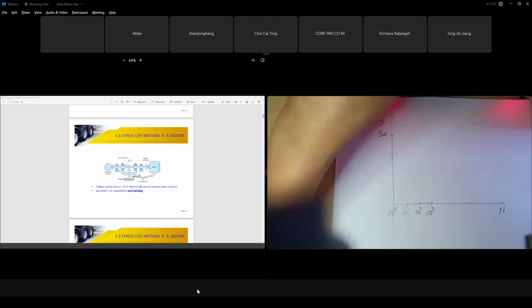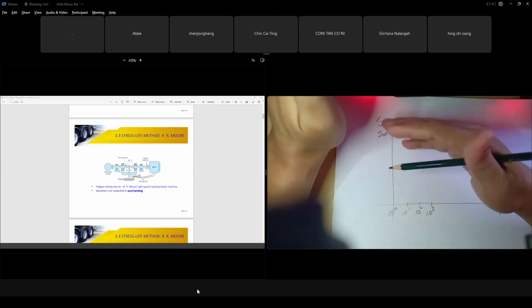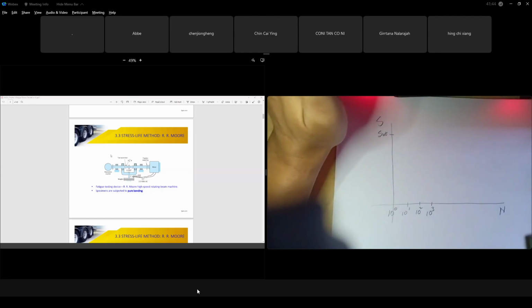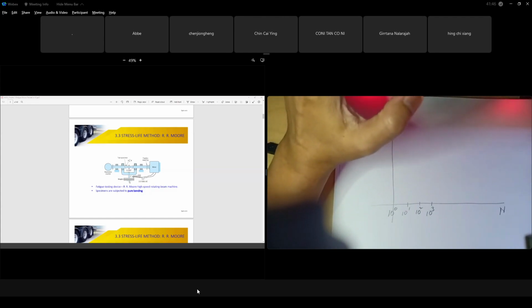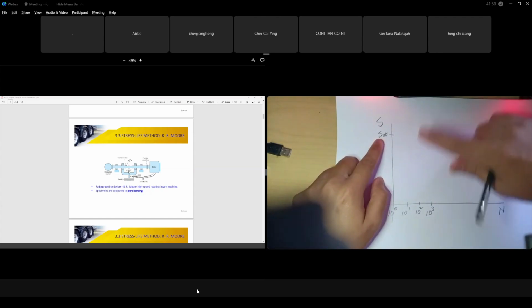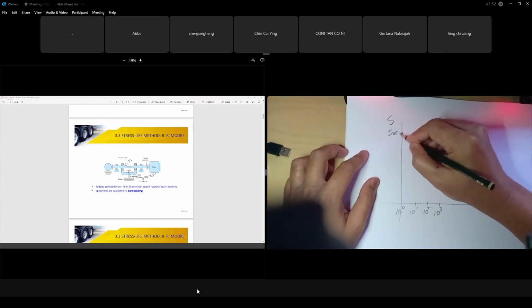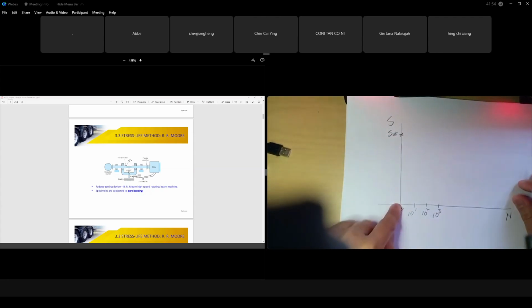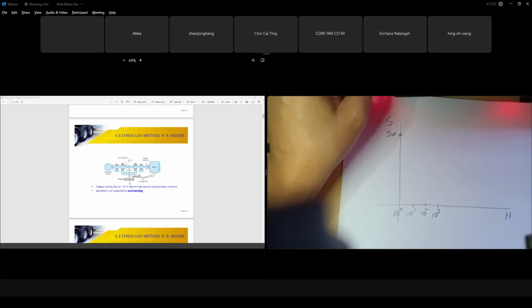It means that if they put a weight so heavy that it reaches the tensile strength of the shaft material, that will be your stress, and with just one revolution it already breaks. That's why they put the data here: ultimate tensile, one revolution and it already breaks. You mean they put the maximum weight that can be supported by this shaft. Then they put a lower weight. Understand me? Are you with me, class?